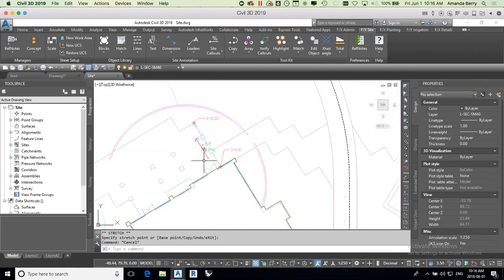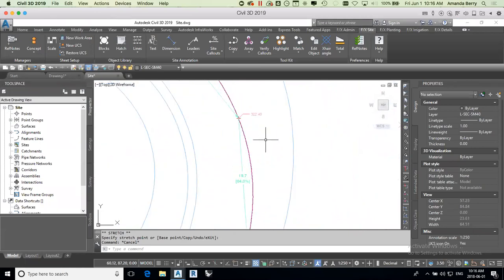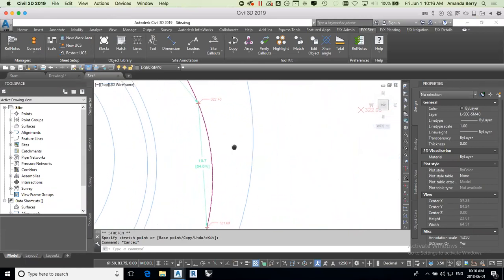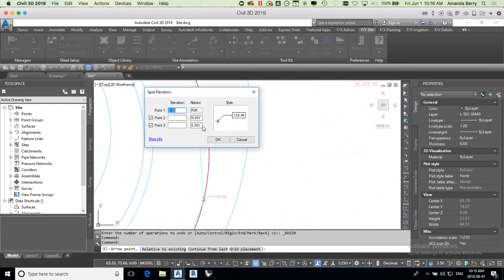So as we go along, we haven't talked too much about contours. If it's a very easy plan like this, you might not even have contours. If you want to show contours on here, you might do a really quick trick. You would draw these manually, but you can save some time on the interpolation calculations by maybe doing something like a spot elevation, put it in at 100. We'll just delete all of these.